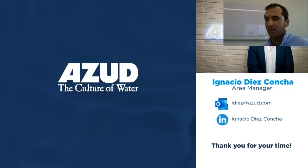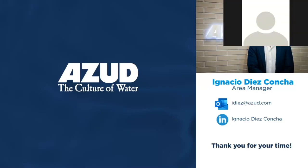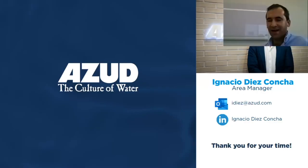Okay, thank you very much, David. Well, with the complexity of the water, you can have very difficult water, even so difficult that you will need another type of technology. But if we remain with suspended solids, which is what the disc filter and other technologies that I mentioned deal with, probably the most difficult waters are the ones from industries such as pulp and paper, where you have many sticky particles, or even textile, where you have filamentous particles.